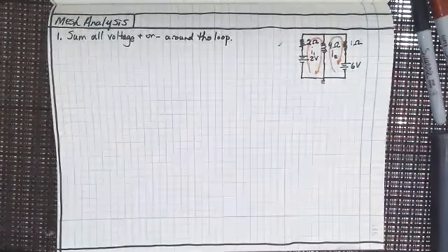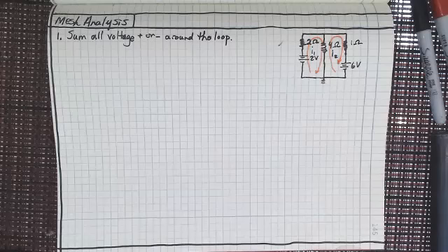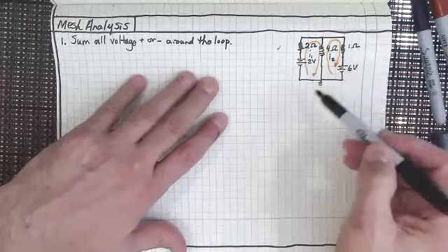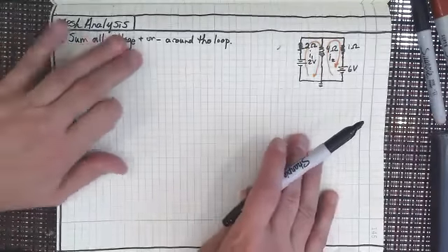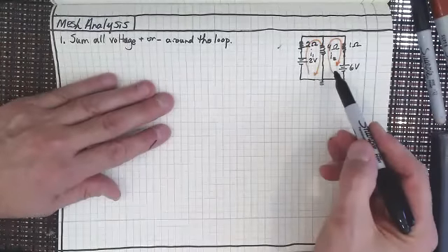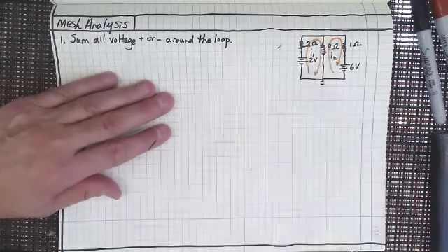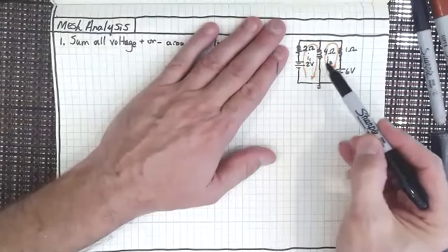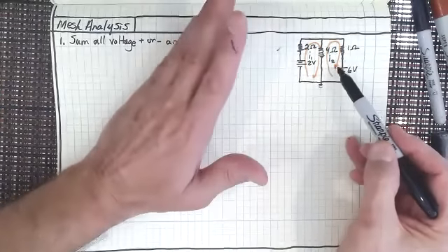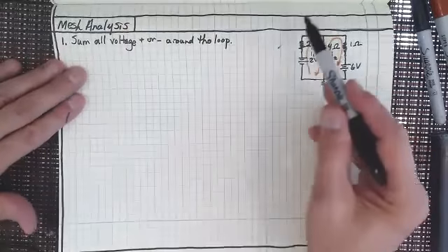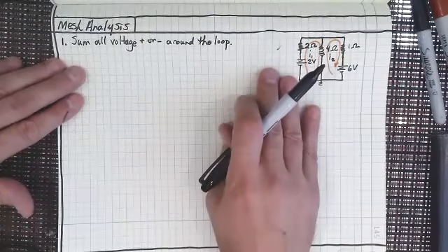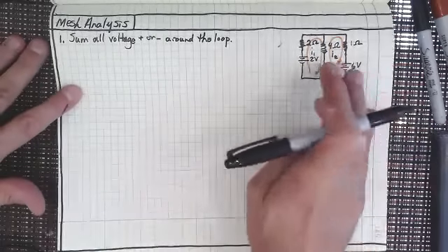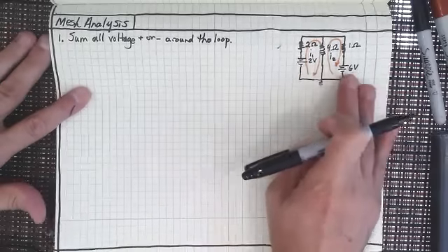Let's just look at, I forgot to put the voltage source for that one. No, I got it. 2 volts, 6 volts, 2 ohms, 4 ohms, 1 ohm. I'm going to do it with a very easy 2-loop circuit first, and then we're going to jump into a 3-loop where it's really much more beneficial. I mean, with this, we don't have to use matrices to solve this, really, do we? Although we could, and I probably will. But with the 3-loop circuit, you really have to use matrix operations to solve that. So let's just do a simple 2-loop, easily using substitution algebra to figure out what's going on here.